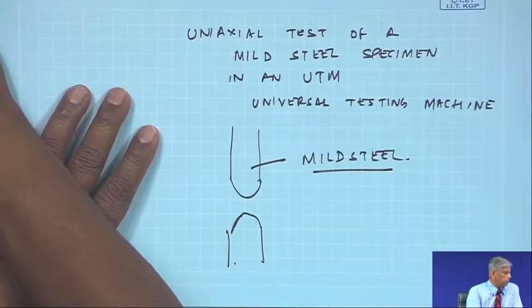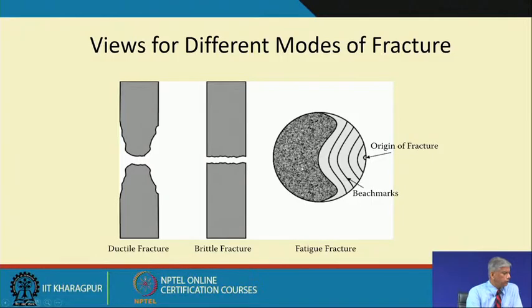In machineries, many of the shafts are subjected to fatigue load, and because there could be a surface defect, surface crack, surface roughness, a fracture would have occurred and proceeded, leaving such beach marks, and finally the area would have been reduced significantly, so that the shaft is not able to take the load anymore, and then there is a sudden failure.